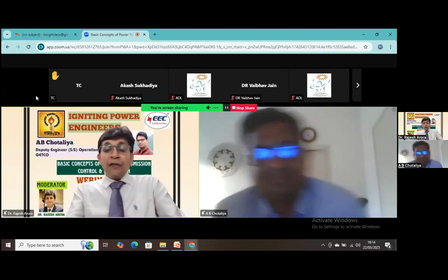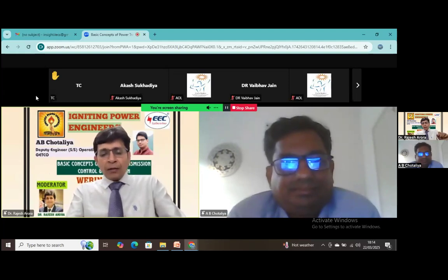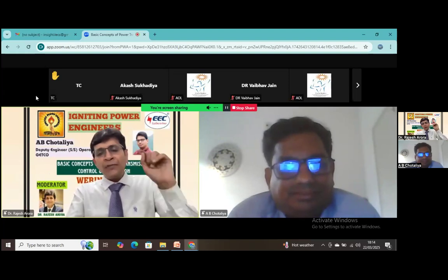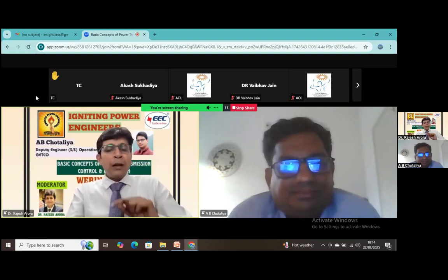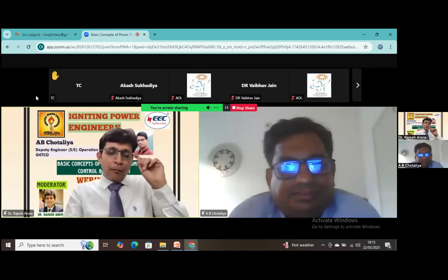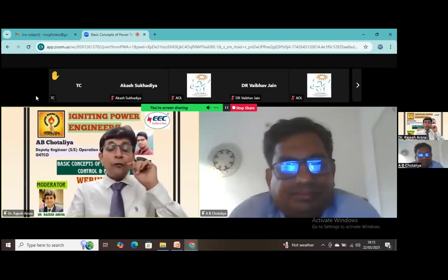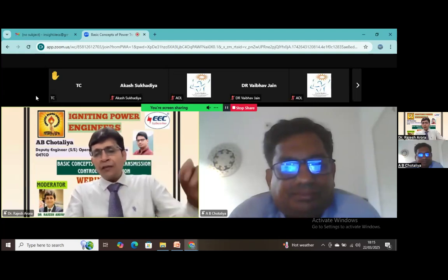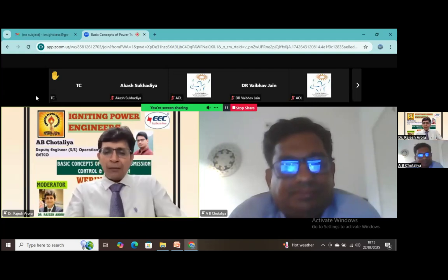When something happens, the fuse should blow or the MCB should trip when some abnormality happens in that circuit. Selection of the MCB and coordination of the MCB and fuses plays a vital role. Am I right, Abhishek ji?